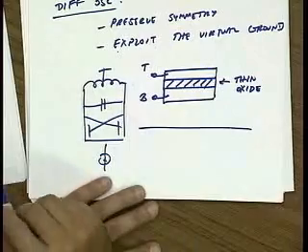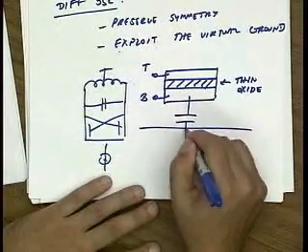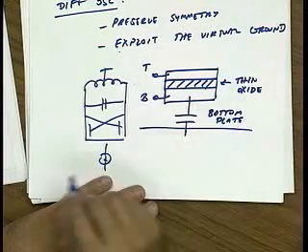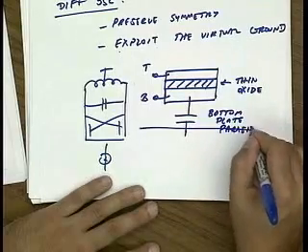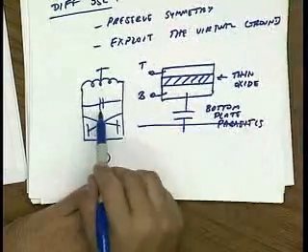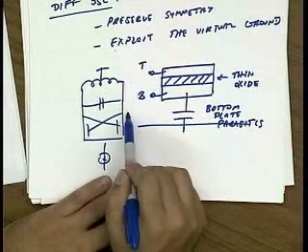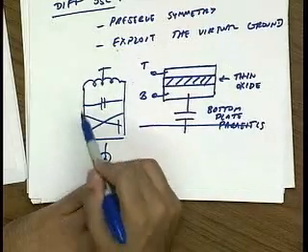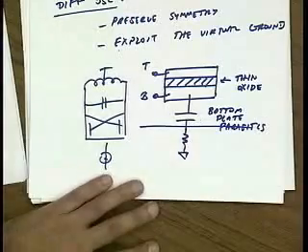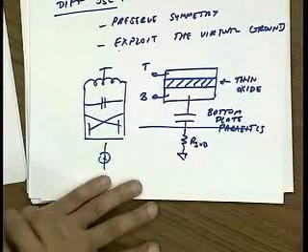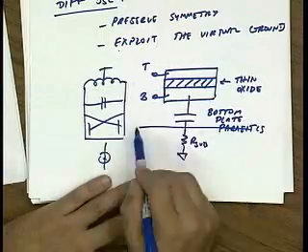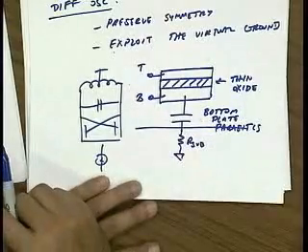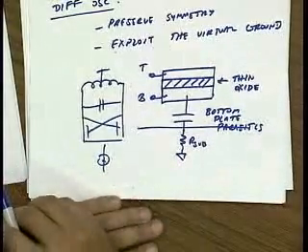Well, of course, this sits right on top of the substrate, so there's the bottom plate parasitics. And that, first of all, if I put this in here, you'd see that it would add an additional capacitance to one side. That's not nice. So what you would do is maybe you'd put a compensating capacitor on the other side. But unfortunately, it's also a lossy capacitor because this substrate is conductive. You could try to shield it. You could put actually a conductor under it to get rid of the substrate resistance, but then the bottom plate parasitics would go up even further, and so the asymmetry would be even worse.